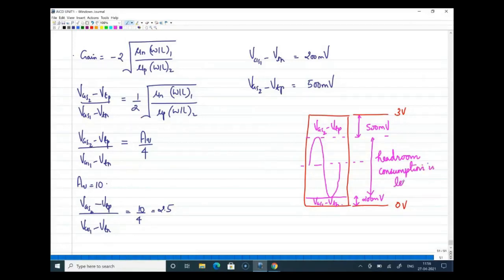less, or I would say output voltage swing at output improved. Do you have any questions on this? So what we did is we added an additional current source, and we observed that because of that additional current source, the ratio of overdrive voltages is not exactly equal to gain. It is a fraction of gain, and therefore we can have a better output voltage swing in this case.